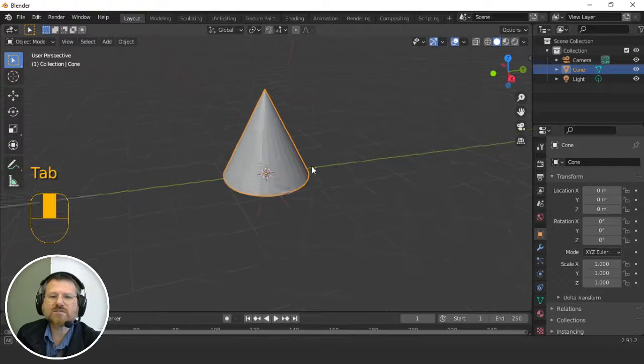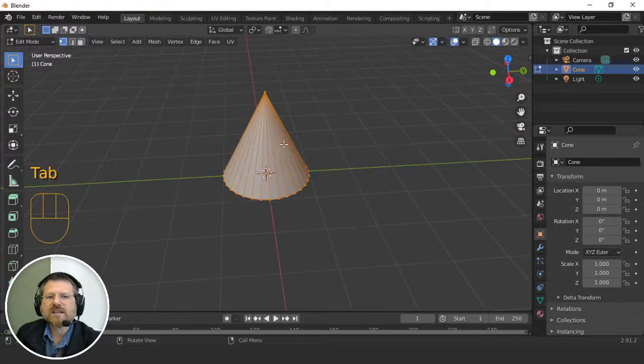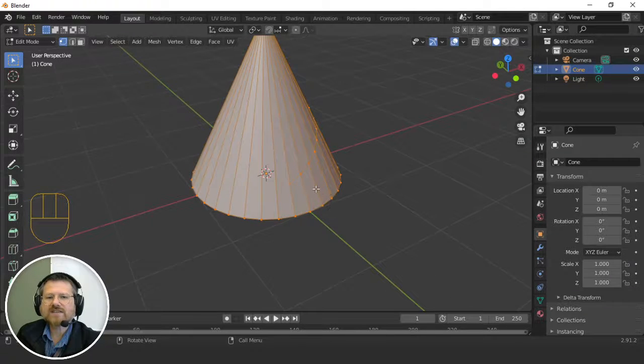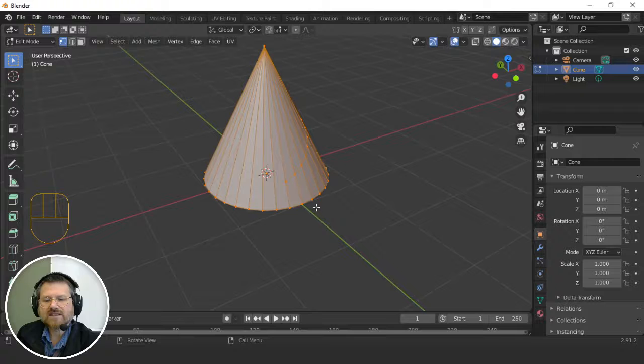And the way the knife tool works is in edit mode, you'll hit K, and notice that here's our knife, and I can literally just drag across. So drag, and then hit enter, and it will finalize that cut. And then I could do the same thing. So if I use my K tool here, and notice it'll snap onto that cut I already made. So I could continue cutting. So cut.